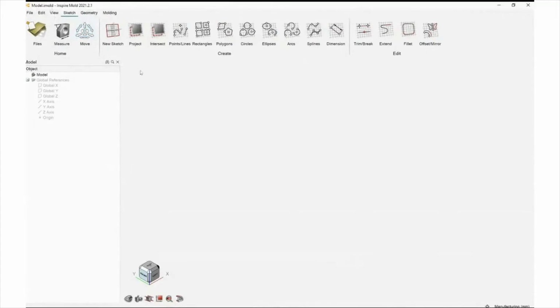Then we've got our sketch tab, fairly straightforward, allows you to create your sketches that you will hopefully be familiar with: lines, arcs, circles, rectangles, and all that sort of stuff. And obviously you can add dimensions to be precise. The view tab is just what you are actually seeing in the program. So I like to have my model browser on, that's why it's ticked, and the model browser is this here. And that will just show my assembly structure or my component structure as I create things.